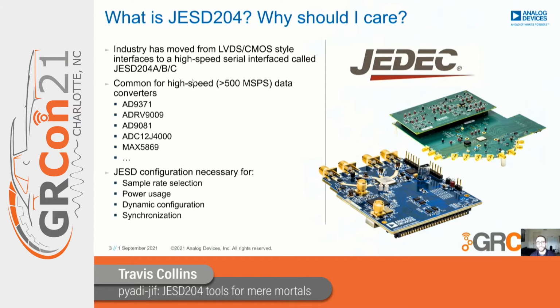So this is really a shift when we're going up in higher bandwidths, where we need to share a lot more data between the data converters and, say, an FPGA or an ASIC. You need something like JESD on transceivers like the 9371 or any high-speed data converter. This is really where the industry has been pushing for the last, I would say, decade. If you're using a device like the one on the right, or something like the Ettus N310, or a high-speed instrument, you'll be using JESD.